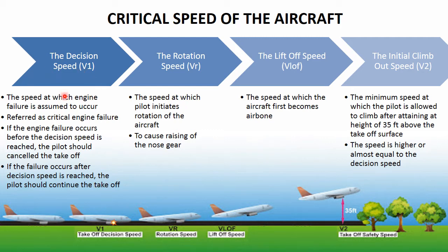And then the rotation speed, or the VR. The VR is the speed at which the pilot initiates rotation of the aircraft. The rotation of the aircraft is to cause a raising of the nose gear. So at VR, the aircraft starts to raise the nose gear.